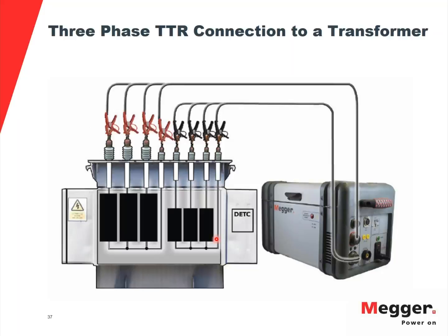Yeah, so on this, TTR you can do on all of them, and I would say winding resistance as well. Just always remember to be within the proper 1 to 15% of the rated current when performing the winding resistance test. So as long as you follow those principles, you can apply both TTR and winding resistance to transformers of all sizes.